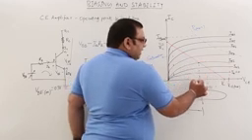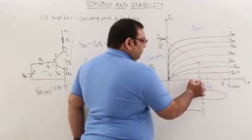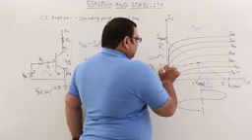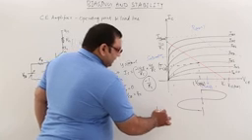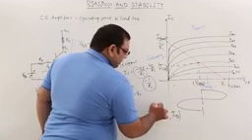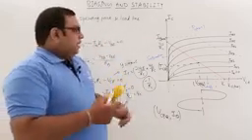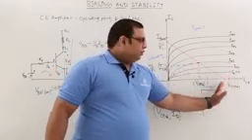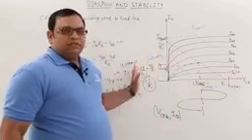This is VCE Q. Q means operating point, and here this is IC Q. So normally we call this point VCEQ comma ICQ. This point is called the operating point for the transistor. When you choose the operating point near to cutoff, the positive portion will be clipped off. When you take it near to saturation, the negative portion will be clipped off.